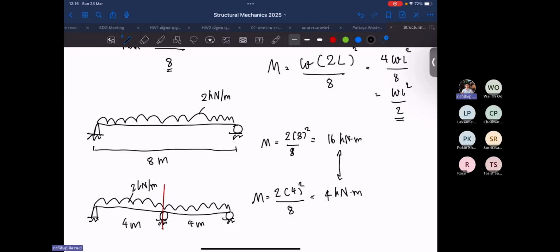I know that sometimes we need a very long span for the scenery or the schematic of the building, but if possible, if we can introduce a support, it can help the structural size. It can save the material cost a lot, because when we double the span, we increase the moment by 4 times.